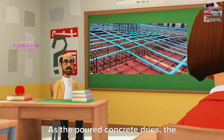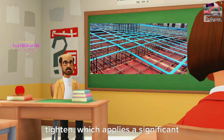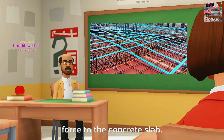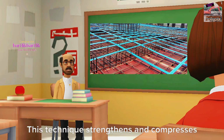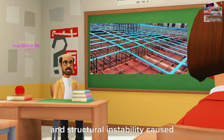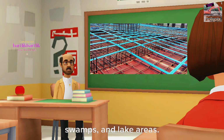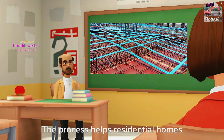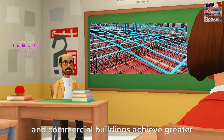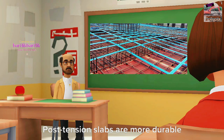As the poured concrete dries, the post-tension cables stretch and tighten, which applies a significant force to the concrete slab. This technique strengthens and compresses the concrete, which helps reduce cracking and structural instability caused by unstable soil conditions in marshes, swamps, and lake areas. The process helps residential homes and commercial buildings achieve greater load-bearing strength.